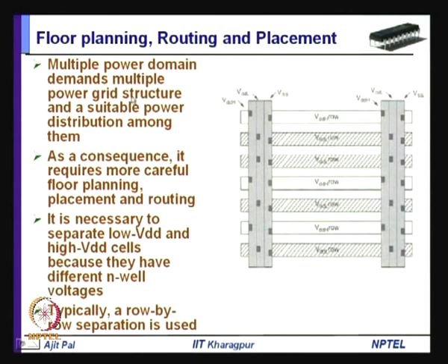Multiple power domains require multiple power grid structures and a suitable power distribution among them. As a consequence, it requires more careful floor planning, placement and routing, as I have discussed. It is necessary to separate low VDD and high VDD cells, because they will have different N well voltages. I hope this point is clear to you.